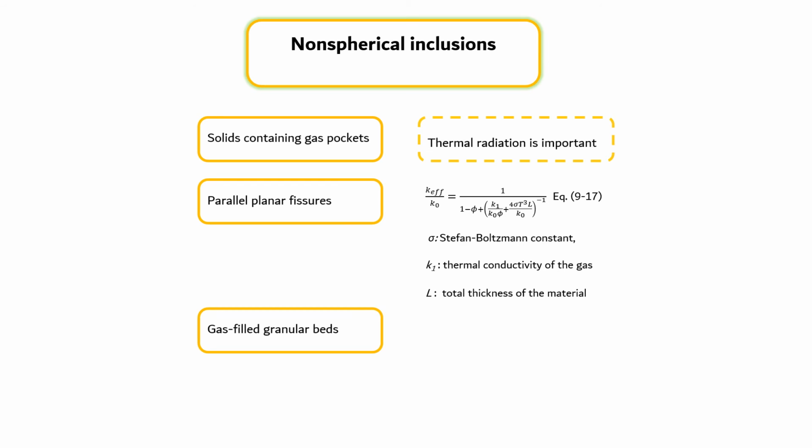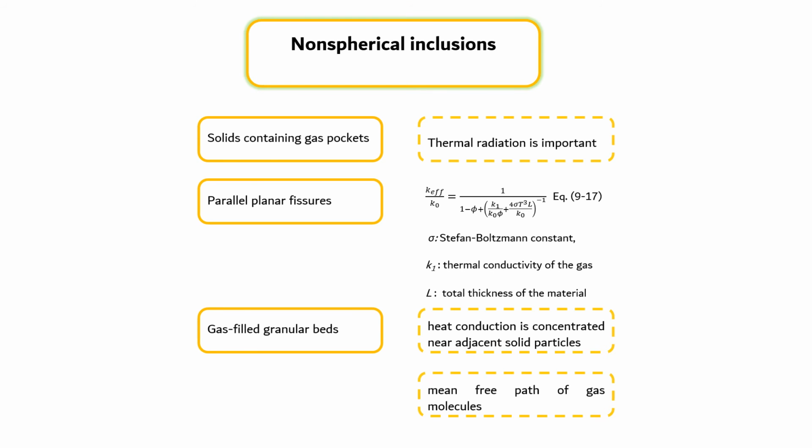For gas-filled granular beds, a different type of complication arises. Since the thermal conductivities of gases are much lower than those of solids, most of the gas phase heat conduction is concentrated near the points of contact of adjacent solid particles. As a result, the distance over which the heat is conducted through the gas may approach the mean free path of the gas molecules. Very effective insulators can thus be prepared from partially evacuated beds of fine powders.